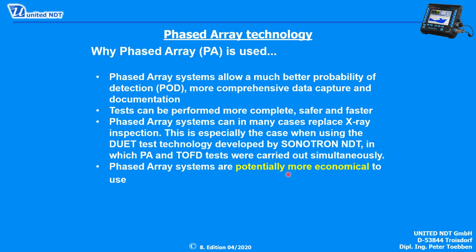Phased array systems are potentially more economical to use, and I put the word potentially because there are so many instruments out there in the market which are very difficult to operate, and it takes a lot of training to get people to a level where they can use and calibrate it properly in reasonable time.